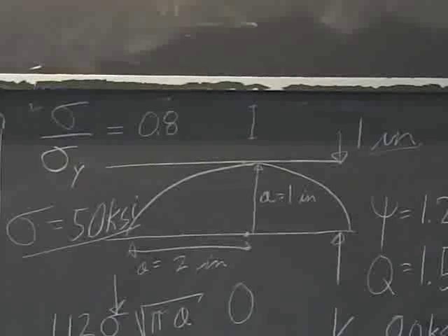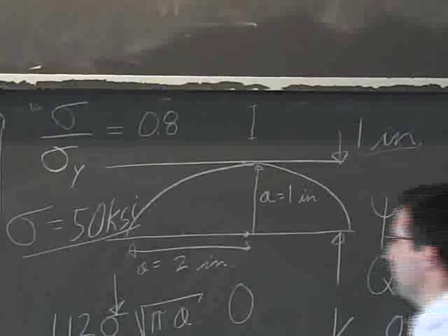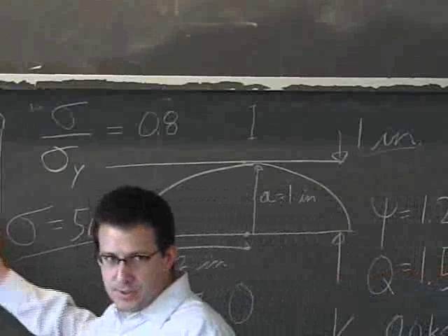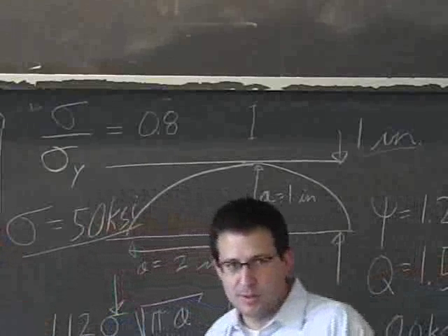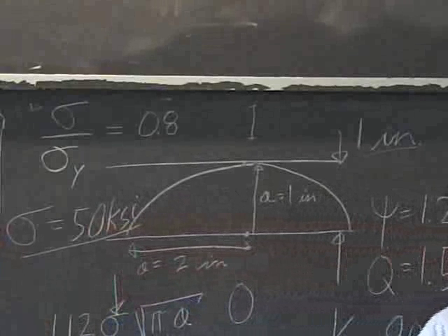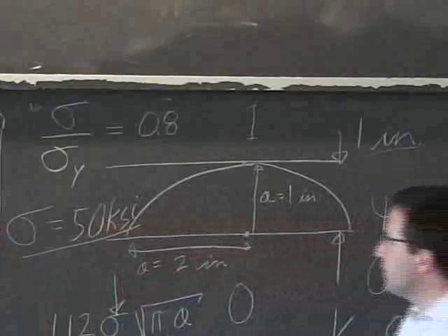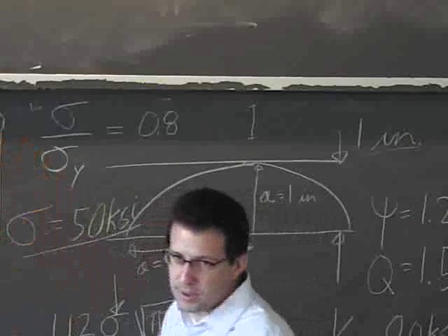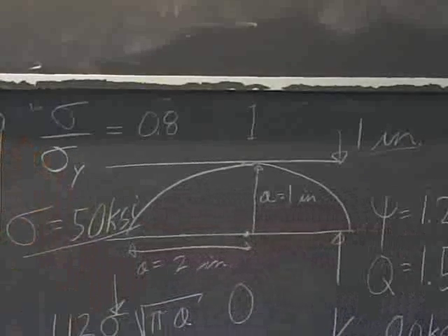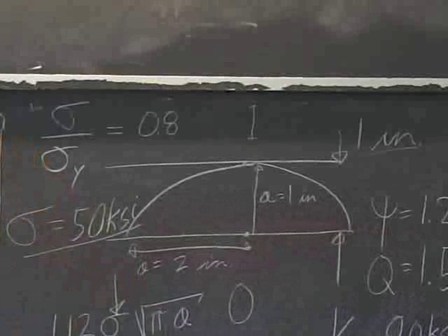And they will go and try to use 100 KSI steel for some applications. When they're doing it, they'll manufacture it so they don't have a seam weld, because that's twice as high a stress. They're only going to have butt joints between sections. The only way to make it work.